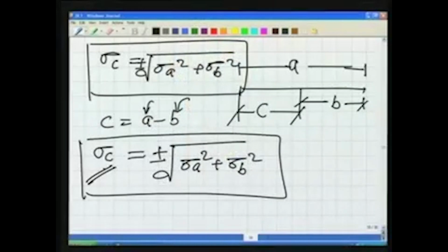Then we talked about the measurement, the basic thing. It will be affected by the error. We must start treating the error. Outliers, well, we have seen we can reject them. Systematic error, we'll see it later on also. If you have any systematic error, you know the physical rule behind it, you can eliminate that also. Now the errors which cannot be eliminated are the random errors, but we have to still treat for them.